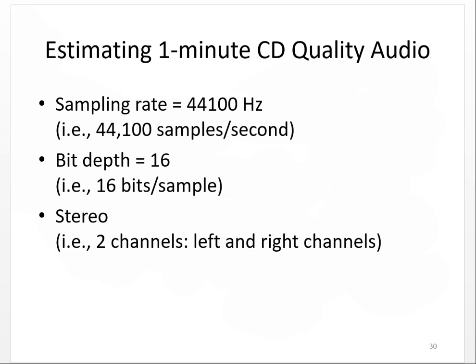So what is our bit depth? Bit depth is 16, which means how many bits are in 1 sample: 16 bits per sample. And what kind of channel are we going to use? We are going to use a stereo channel, because it is audio quality sound. Stereo is 2 channels, left and right.